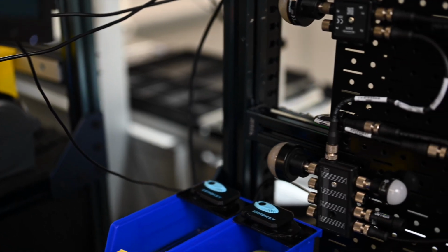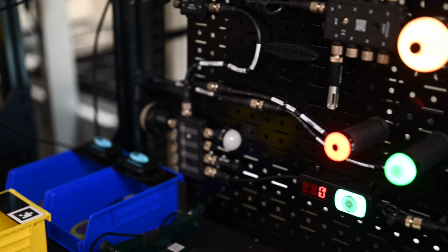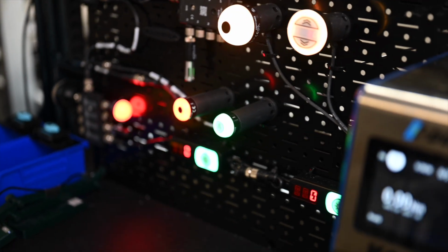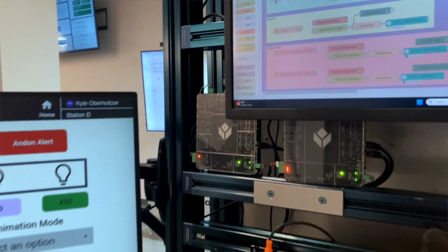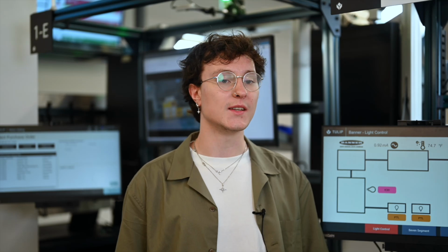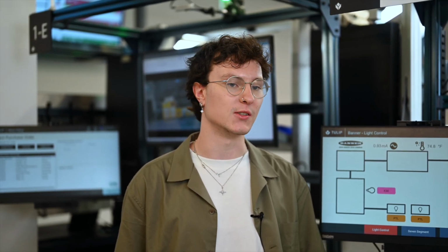These junction blocks attached to the pegboard are all connected to Banner's Modbus-enabled lights and sensors and are all routed to an edge I/O using a singular RS-485 cable. This way, you can configure a number of devices without needing much additional hardware. All of these devices are configured using Modbus nodes from within Node-RED that communicate directly to your Tulip instance using Tulip tag nodes and connectors.